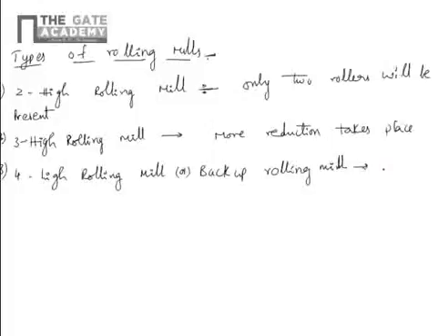So here we use smaller rollers such that the force generated or stress developed will be less. If you use smaller rollers, we need to use a small shaft, and there is a possibility of the shaft breaking. To avoid that, we use supporting rollers. In this layout diagram, one small roller, and here a supporting roller. To support this roller, we use another big roller.